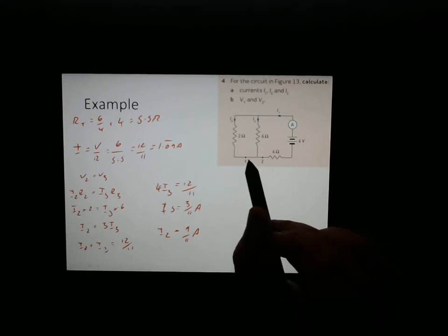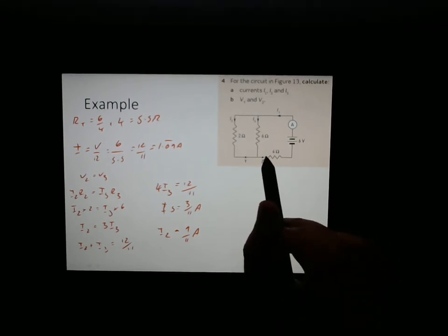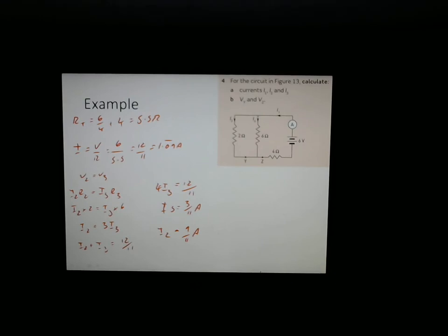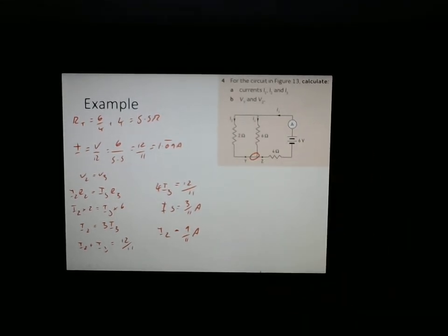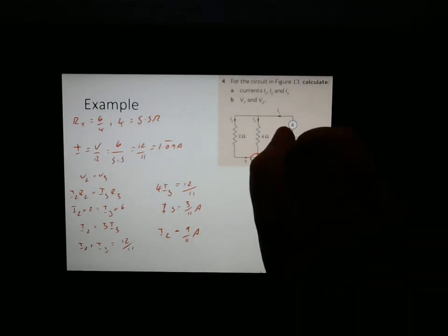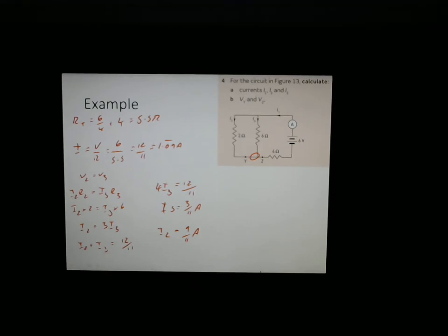So note from here, from Y to Z, on that first loop, it didn't actually lose any voltage. There's no element here between Y and Z. So it doesn't matter that the two loops have not rejoined yet. It doesn't matter that it's separate. The voltages will be the same. Now, in reality, that's not true, because wires do have resistance, but we pretend that they don't have resistance for the sake of these problems, just to avoid dealing with that issue.